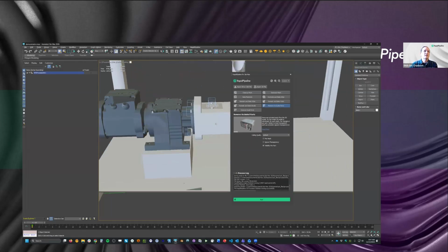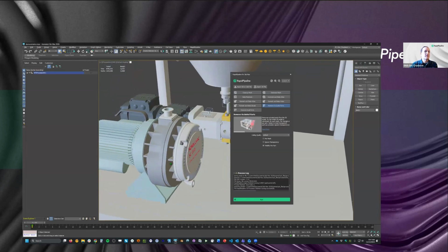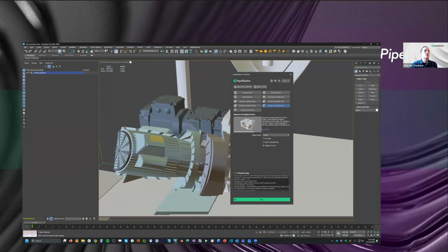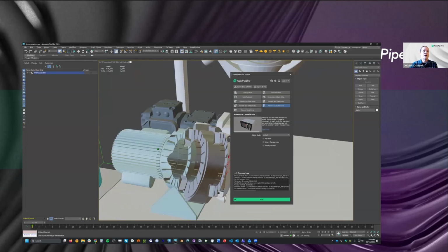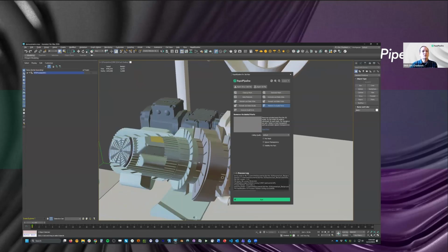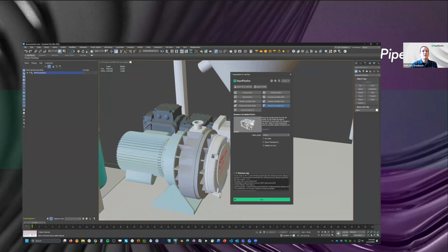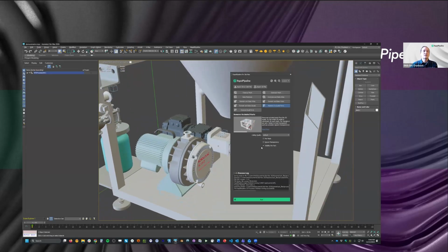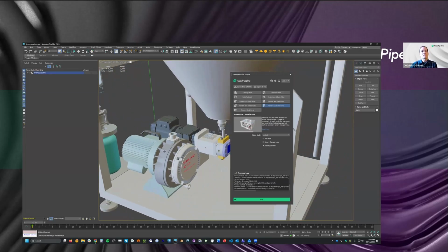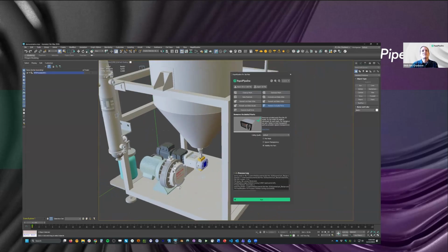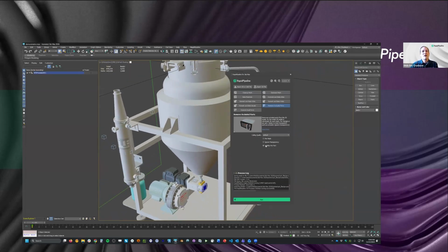And then visibility per part will look at how to remove the parts that it finds. For example, if it looks inside of this mesh thing down here, inside of this engine, it'll try to remove whole parts in visibility per part and basically work on the element level of meshes and remove full elements. If you turn this off, it'll go on a per triangle basis and it'll cull individual triangles that it finds that are not visible from the outside. So generally, as a 3D artist, I don't like having a bunch of floating triangles inside of my models. It just looks really weird. I'd rather have it cull out whole parts.